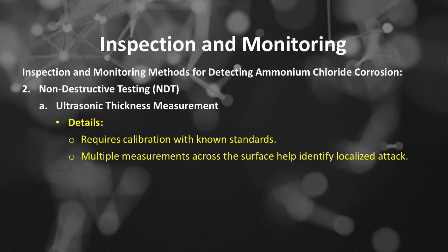The details of ultrasonic thickness measurement are: it requires calibration with known standards, and it can do multiple measurements across the surface to help identify localized attack.